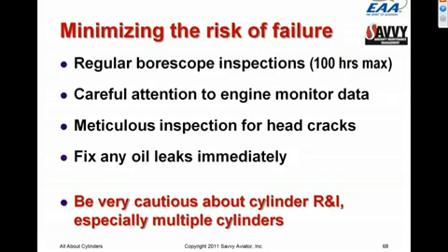Finally, minimizing the risk of catastrophic failure, cylinder failure. We want to do regular borescope inspections. Every cylinder should be inspected with a borescope at no greater than every 100 hours. For the average owner that flies 100 hours a year or less, doing a borescope inspection at annual is fine. But if you fly the airplane a lot, 200 or 300 hours a year, doing it once a year isn't enough.